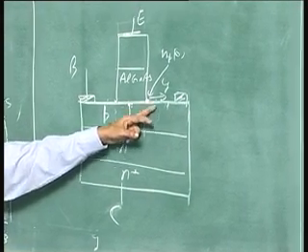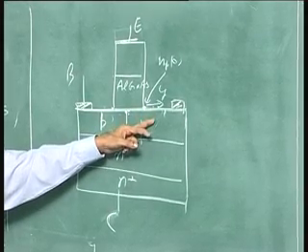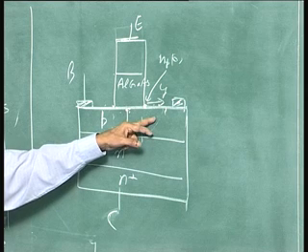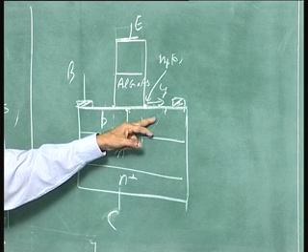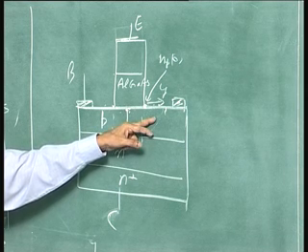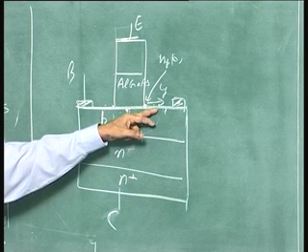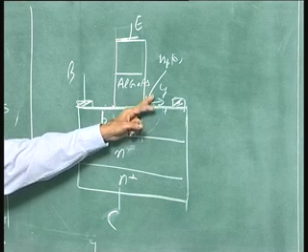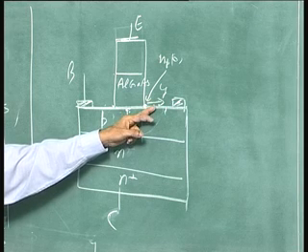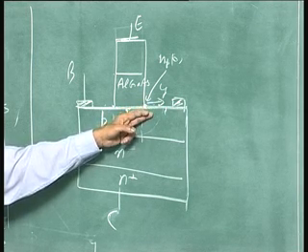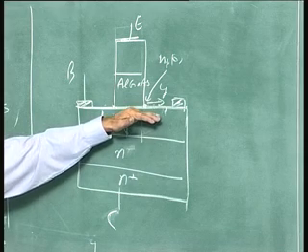These atoms in the bulk, they are surrounded by 4 neighbors. So, all those bonds are tied to each other, there are no dangling bonds. Whereas, here the atom sitting on the surface has 3 neighbors below, no neighbor here. So, a dangling bond is up there, which is very highly reactive, and that is the one which acts as a recombination center. It is a deviation from the periodicity.